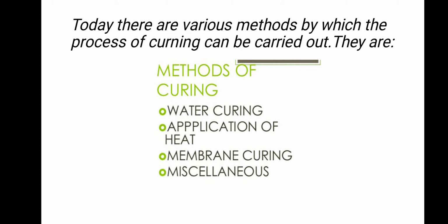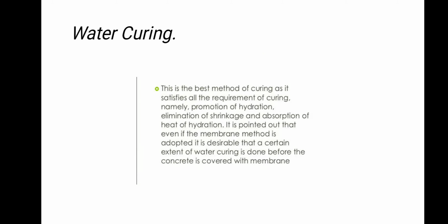Water curing is the best method for curing as it satisfies all the requirements, namely promotion of hydration, elimination of shrinkage, elimination of cracks, and absorption of heat of hydration. It is pointed out that even if another method is adopted, a certain extent of water curing is done before concrete is covered with membrane, that is, in membrane curing.